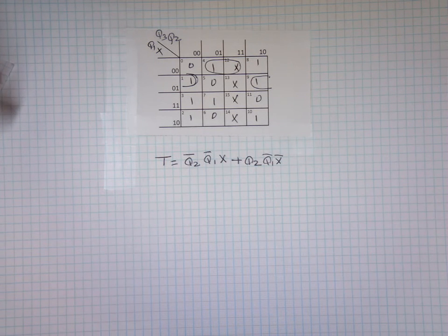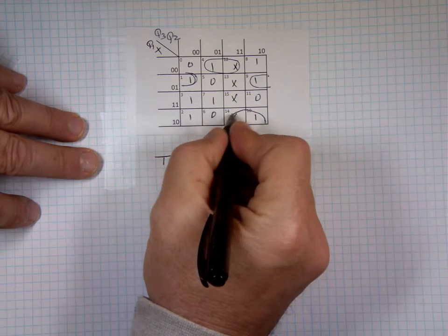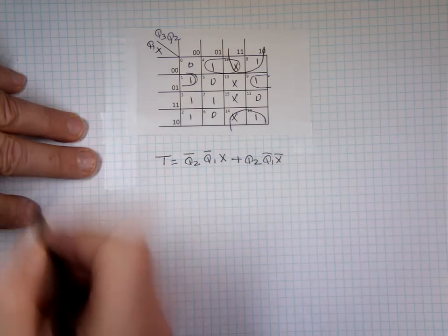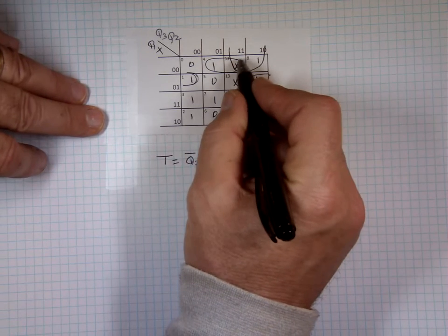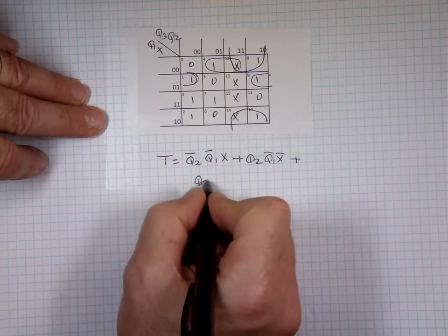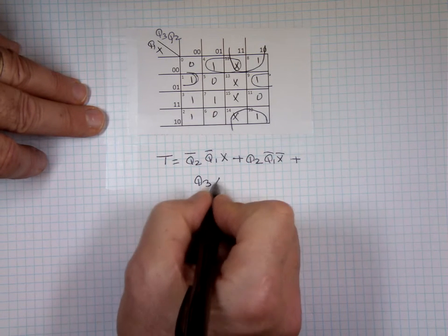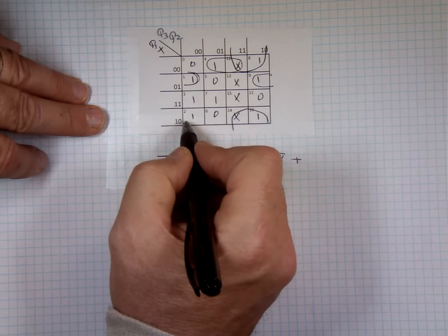Now I'm looking here. I would agree with Lucas. I would go top right, bottom right, because you get the bars out. It doesn't really matter. Yep, it's still going to be 3. I'm trying to see if I can eliminate 1. You're going to be overall the same no matter what you do. I just want to get rid of something, but it doesn't look like I'm going to be able to get anything out. There's tiny NOT gates there, right? So that will be what? Q3, then, and X naught. Oh, there's another one next. Oh yeah, yep. Okay, never mind.